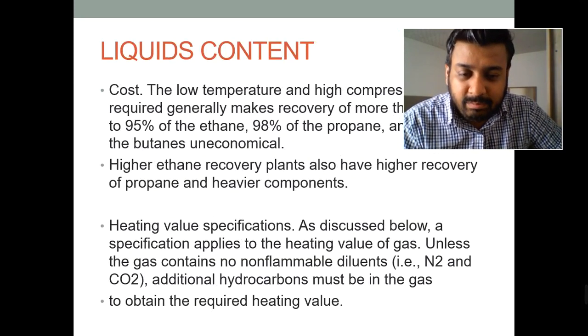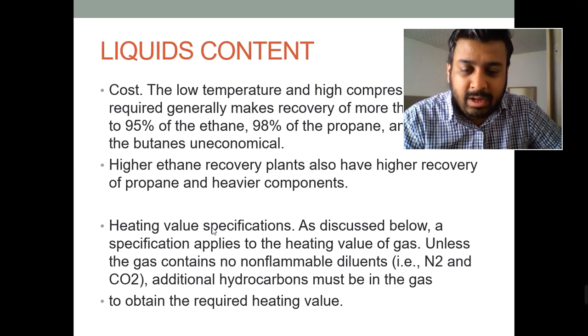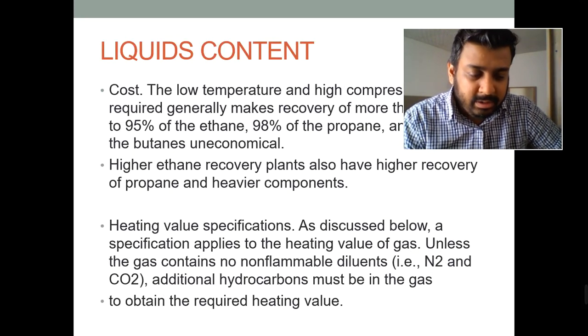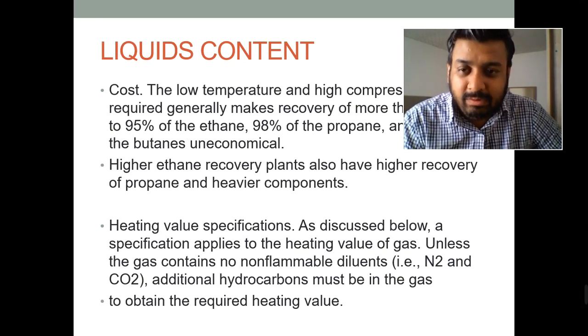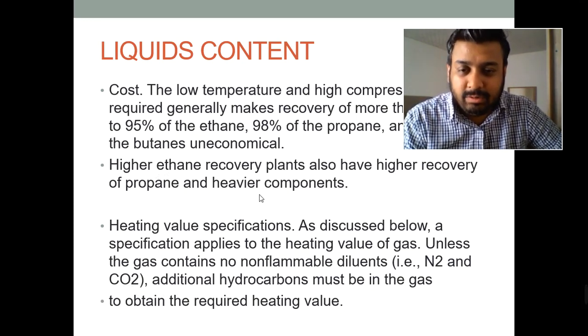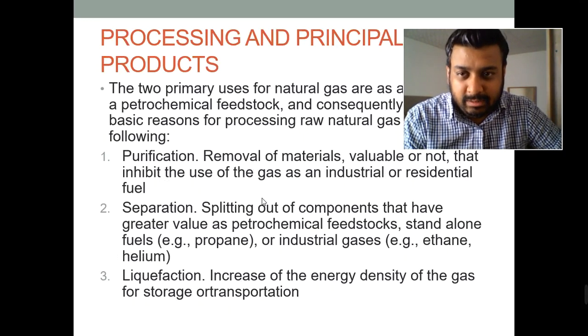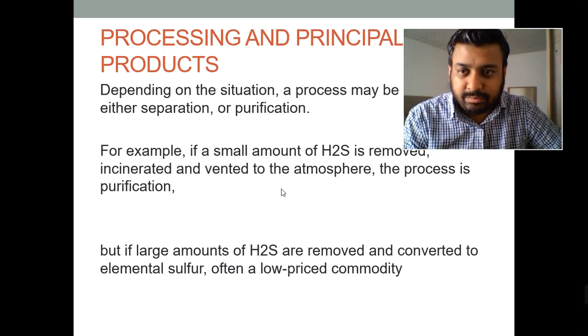But sometimes we leave them intentionally, because if the gas has nitrogen or CO2, they reduce the heating value, and a higher amount of heavy liquid hydrocarbons may increase the heating value of the gas. So if the heating value needs to be maintained, then we add the heavier hydrocarbons so that we can keep the gas at the standard conditions.